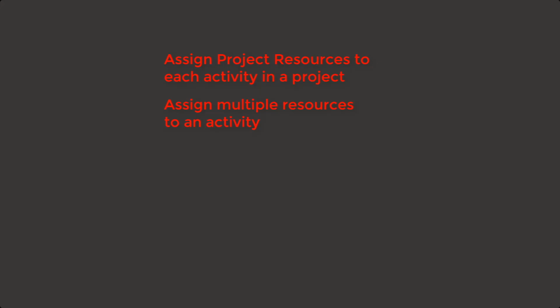To recap, in this lesson we learned how to assign resources to each activity in a project, assign multiple resources to an activity, and view all resources assigned to the current project. In the next lesson, we will look at activity and resource usage and assignments in P6.